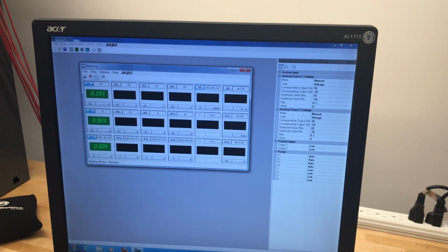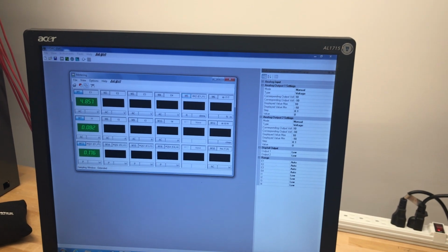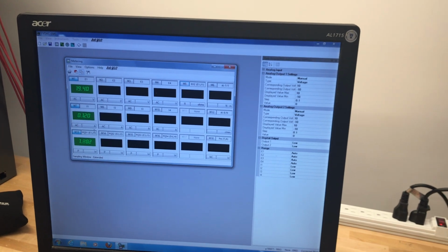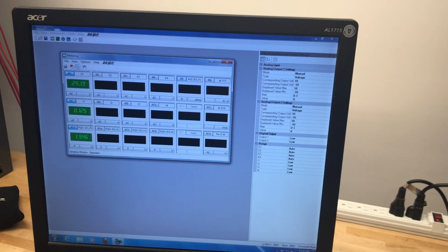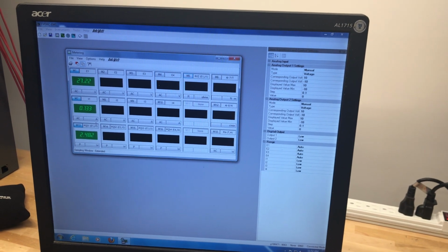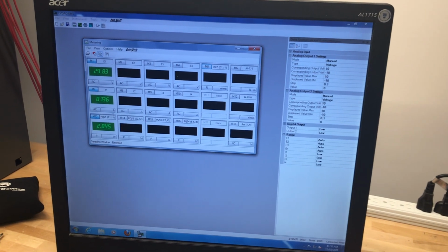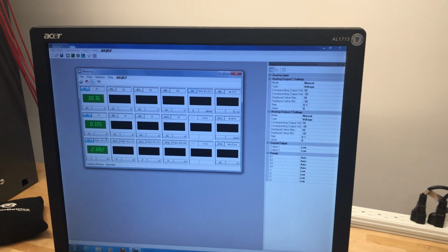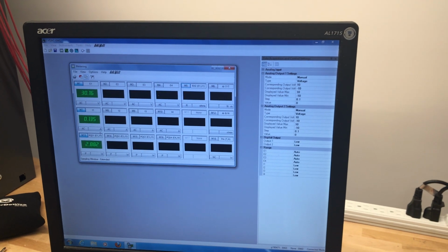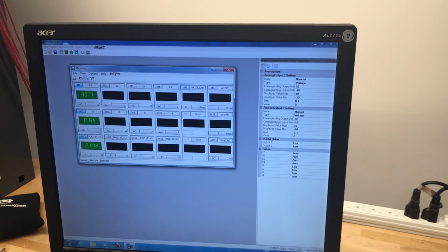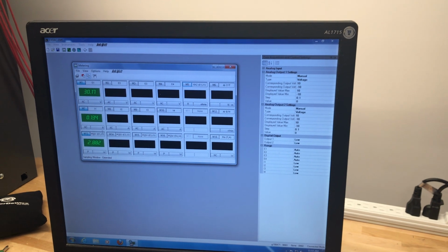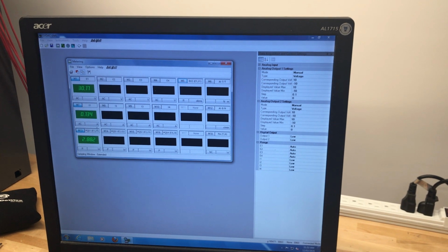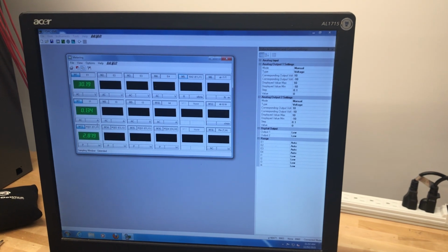and then I will start changing my input voltage. I'll take different measurements, not only one, because he asked me to do that. For example, this is the first one, which is Vn 30.15, and I1 is 0.135, and the power input is 2.87.